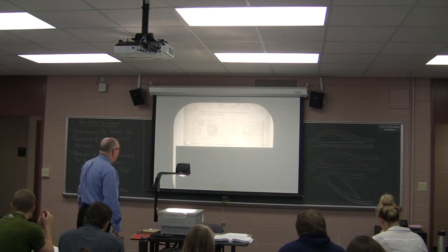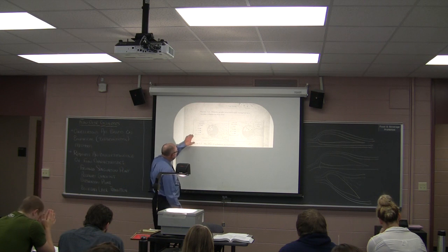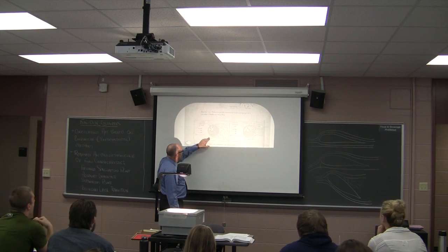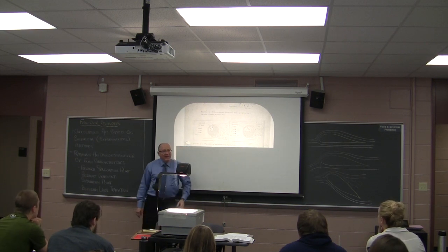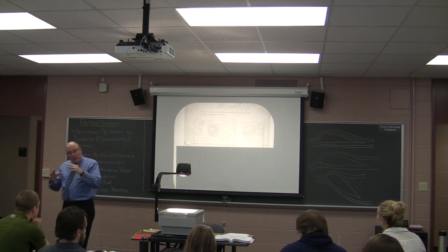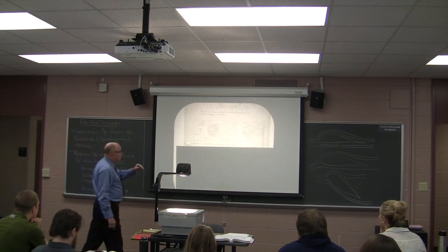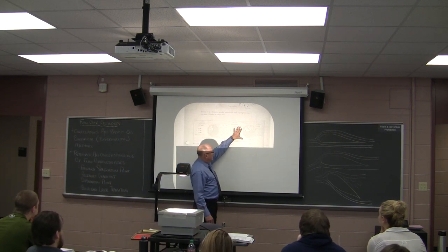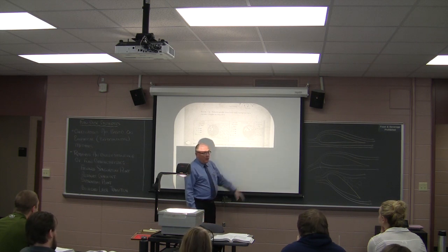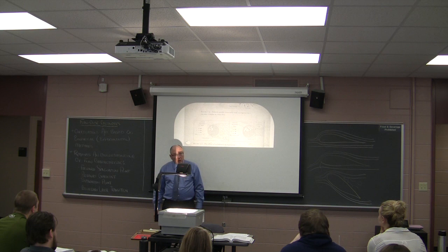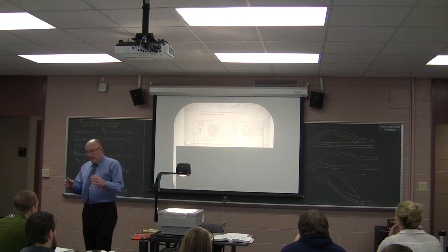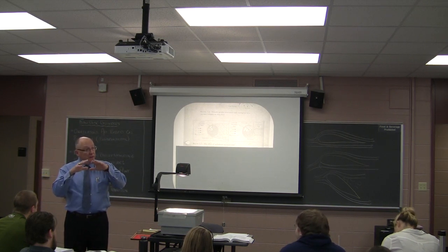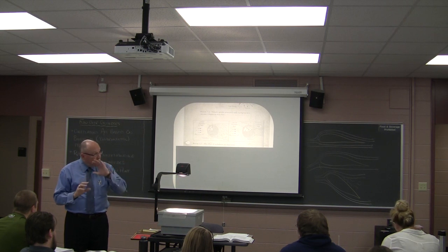Now, if we take a look at this ball, or this cylinder, we have formation of a laminar boundary layer, and what typically happens with the laminar boundary layer is there's not enough energy in the boundary layer to adhere to the cylinder. So with a laminar flow, you get separation at an earlier angle than you would if you had a turbulent flow. So turbulent flow with more energy keeps the boundary layer adhered. And we've already talked about that on an airfoil, where you can see it on commercial airlines where they rough the surface of the wing.